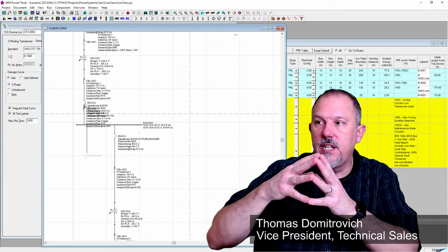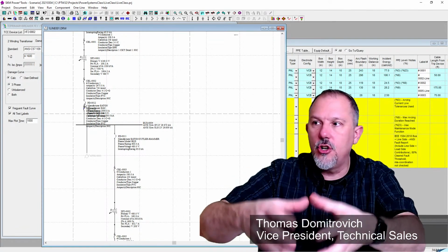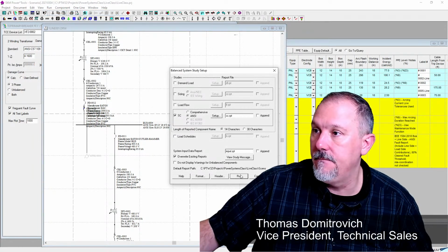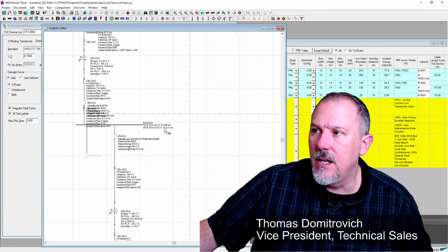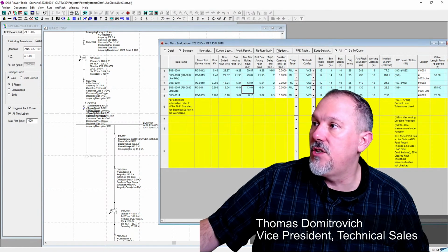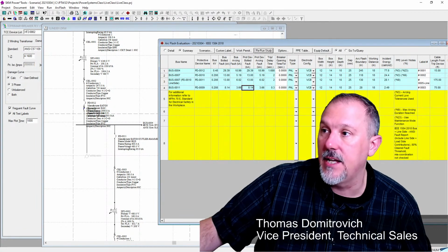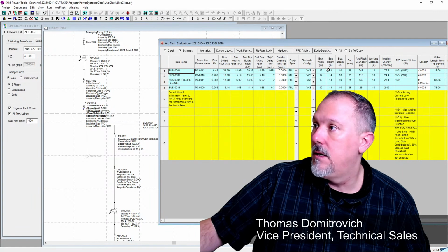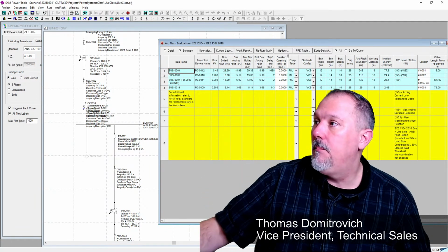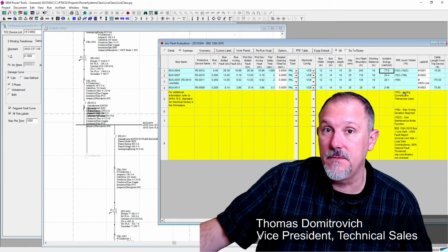So now we're taking PD12, putting it in its own enclosure outside of this bus. We're going to run the short circuit study. We added a little length of conductors so it reduces our fault current a little bit. But what does it do to our incident energy? Now look, that 100 and some calories at bus 4, bus 4 doesn't have two values anymore. Why? Because there's no main breaker in there, but it took the 106 down to 77.8 calories.